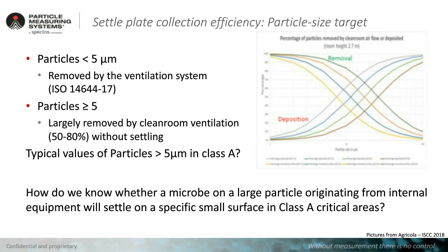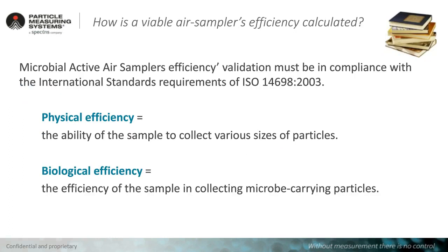So let me change a bit to the active air samplers. Viable air samplers have a certain efficiency, and there is a standard here. The standard is ISO 14698 from 2003. This was a standard that was already quite modern, I must really say. The ISO 14698 had all aspects of risk assessment already included in the year 2003, when in our world of pharma, it was not even considered in our regulations.